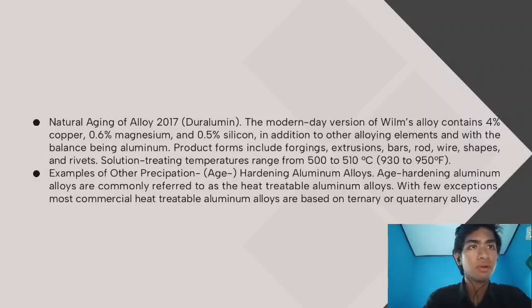Quenching is performed in water at room temperature and should not be allowed to drop below 38 degrees Celsius during the quenching cycle. Cooling from the solution treatment temperature to room temperature must be complete within approximately 10 seconds. Aging takes place at room temperature over a period of several days.